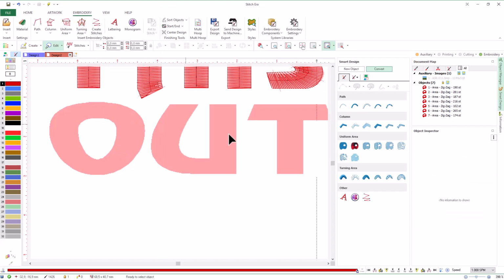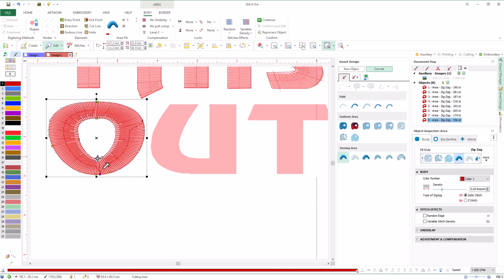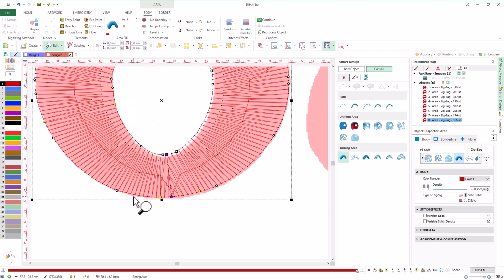Select turning area with zigzag and autocomplete. Click to capture. As we can see, unlike auto trace, autocomplete captures all the contours of the region, and not just one of them. Select Accept in the context menu and check the object. Autocomplete added a cut line and direction lines, as expected. However, it added direction lines at each side of the cut line to get a result similar to the cut line and direction combination we used before.